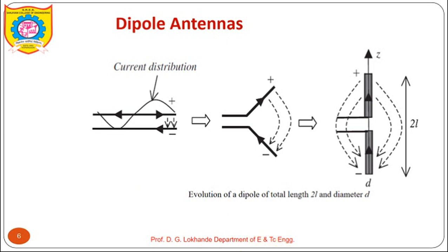But in the two-wire balanced transmission line, the current in the half cycle of one wire is of the same magnitude but 180 degrees out of phase. In addition, the spacing between the transmission lines is very small, so the fields get cancelled and no radiation takes place in the transmission line. In another figure, we can see a flared component. This is part of the transmission line where the source is feeding one end and the other end of the transmission line is opening out.